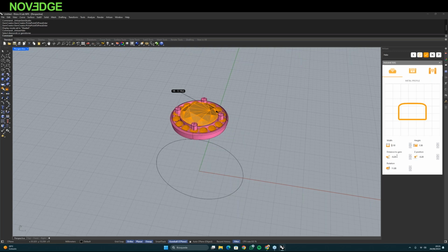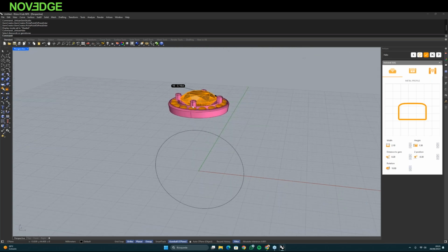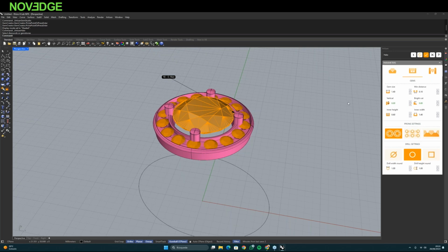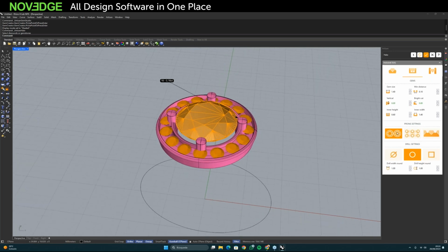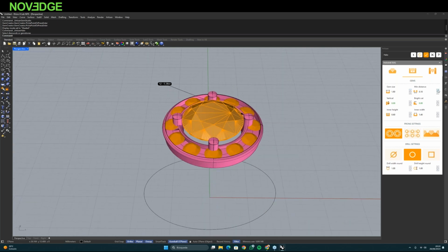The thickness is okay. The distance from the gem, I'm going to increase it to 0.2, and I'm going to reduce a little bit this, and I'm going to reduce the inclination as well. And yeah, like this. Okay, so now it is in the channel setting option, but we are going to change that. But before, I'm going to change the size of the diamonds to 1.8, and I'm going to keep a distance between them of 0.2 mm. I'm going to keep it here in vertical 0.